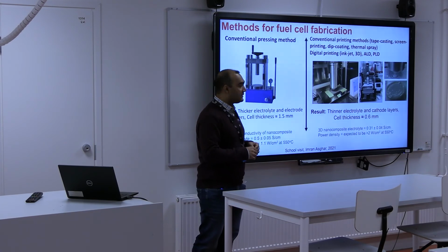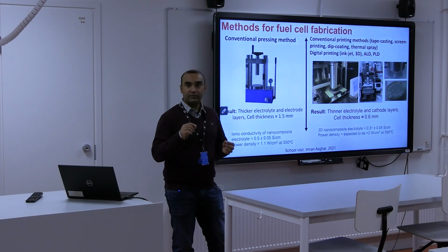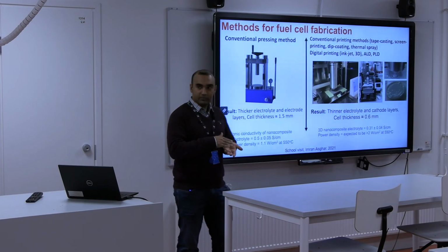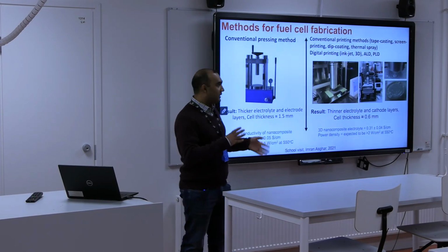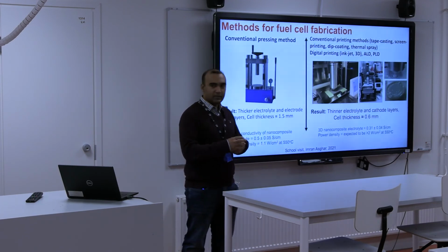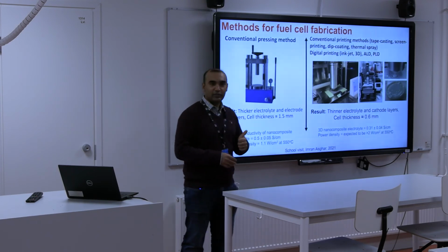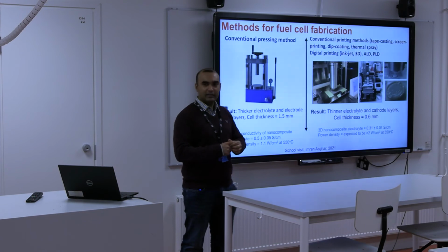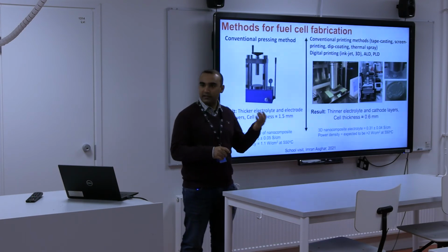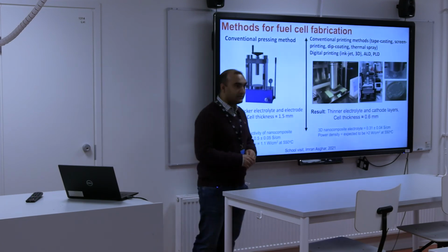But nowadays, it's also a very hot topic in research to make even hundreds of nanometer thick layers. For that, printing technologies are not so good because they mostly give a few microns thickness. For that, there is ALD, which I think is a Finnish innovation. In the 1980s, some professor at the University of Helsinki invented atomic layer deposition techniques, or we have pulsed laser deposition techniques.